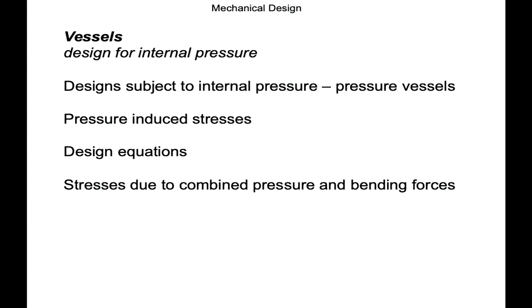Often steel, mostly steel, we get the release of that gas at a sonic velocity. So the steel will just peel away, the vessel can easily turn into a rocket, and if we've got heat plus release of gas, there's something called BLEVE, which I'll talk about later. It's essentially an explosion plus rocket, and very, very serious consequences.